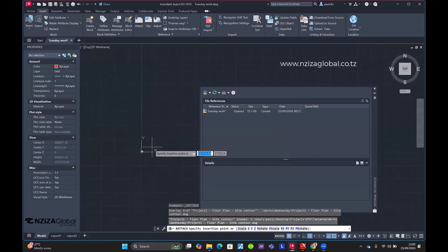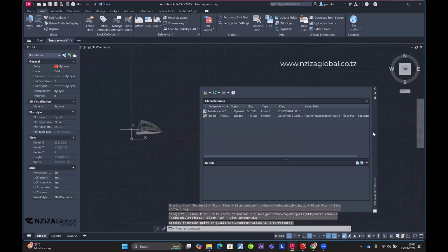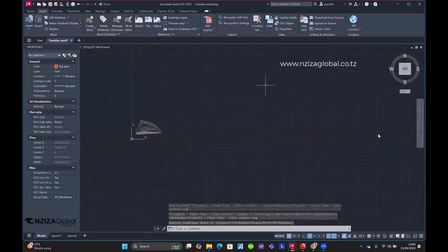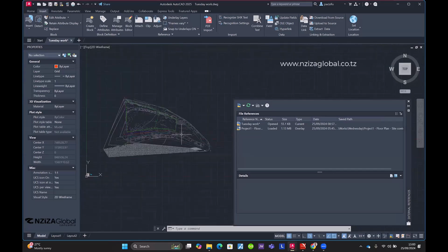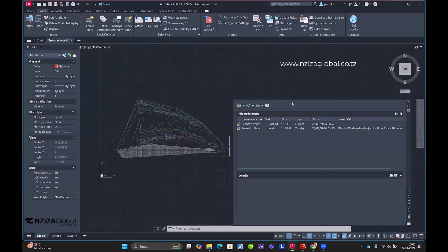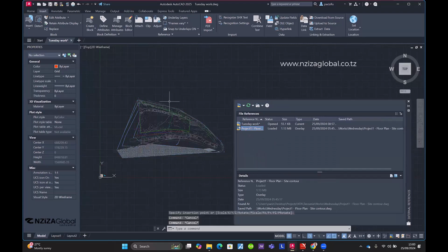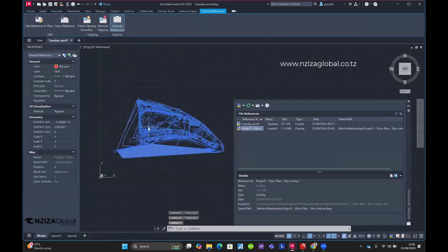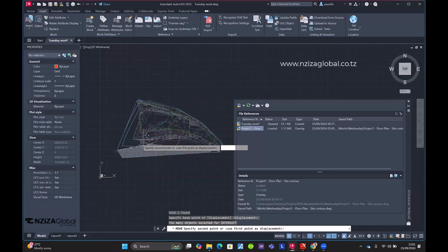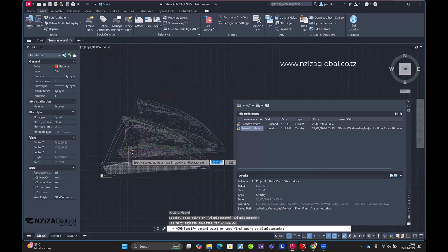So we have to locate our drawing. We may take it just here. Then let's move this a bit. Then I can come in this external reference property. I select the drawing, so it will be shown like this in blue. Or let me just try to select outside of the property, then make a move. Aim, enter. Then move a bit toward those axes.